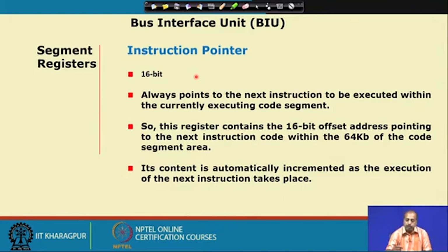This automatic incrementation is very much possible because you have got a dedicated adder in the bus interface unit. So, you can use that adder for doing this addition without affecting the ALU that we have in the execution unit.